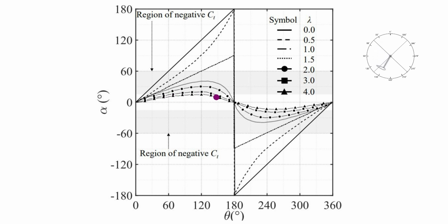An angle of attack of 10 is still smaller than a static stall angle for most airfoils. If the angle of attack never exceeds the static stall angle, then dynamic stall never happens. But if it does exceed the static stall angle, then dynamic stall happens. So in this scenario, for most Darrieus turbines, dynamic stalls tend to occur only between the tip speed ratios of about 0 and 3. But what exactly are dynamic stalls on Darrieus turbines?